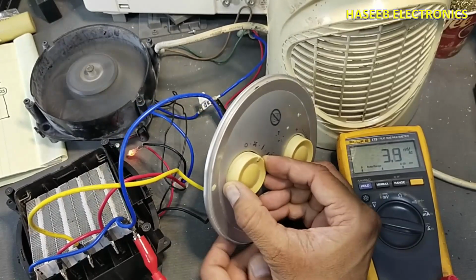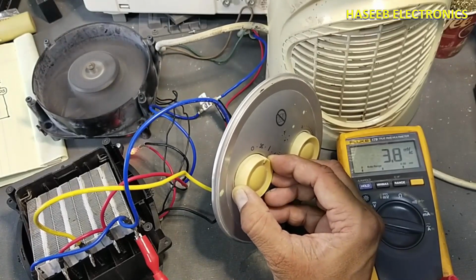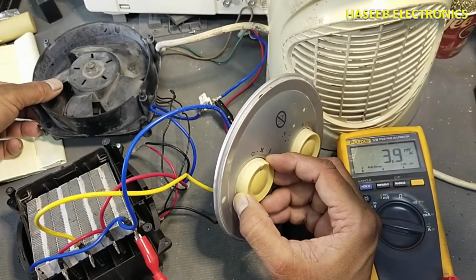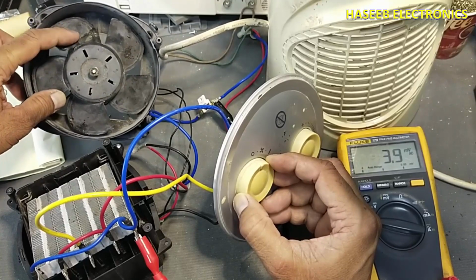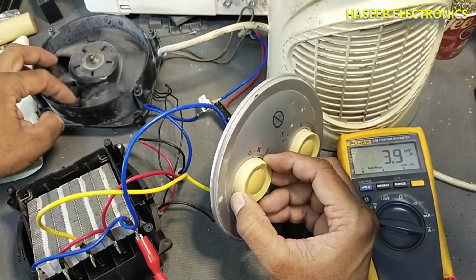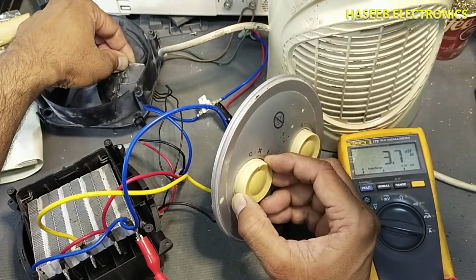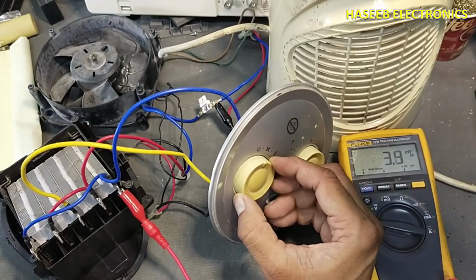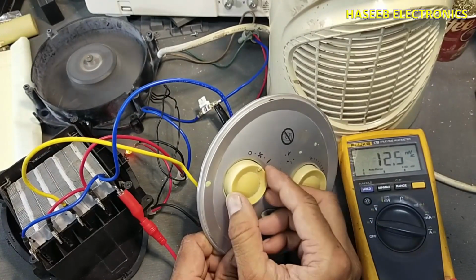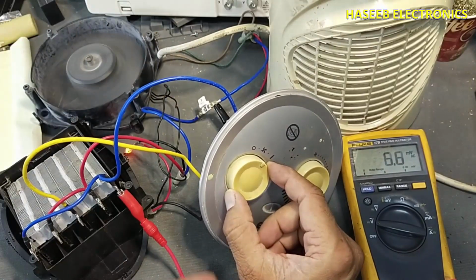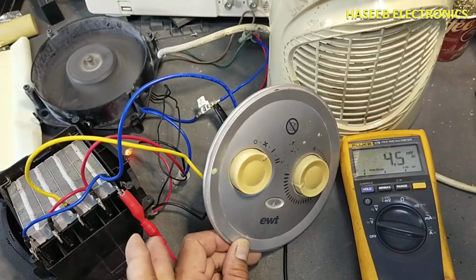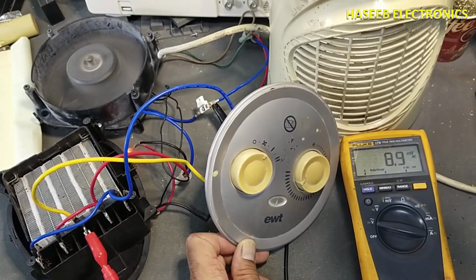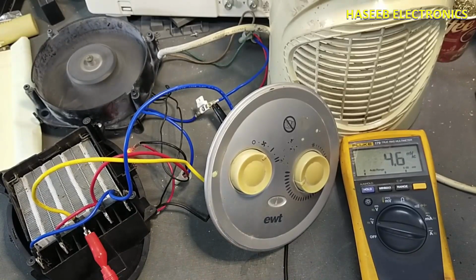Turn on the switch. The fan started. This time the fan has an abnormal sound. Why? Because one of its wings is broken and someone applied some epoxy hardener. Now it is unbalanced due to the extra amount of epoxy, so it is heavy on this side, so it will not rotate properly. Now only the fan and the neon are working, and we have no voltage at this low terminal. No voltage at low terminal, low heat, and no voltage at high terminal. Just the fan is operating.